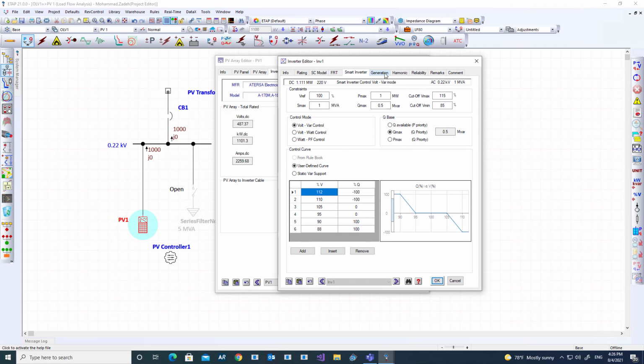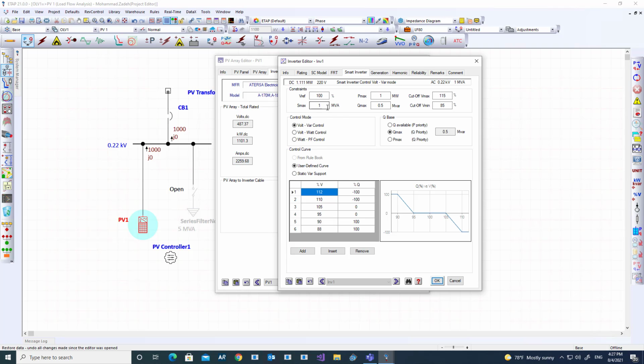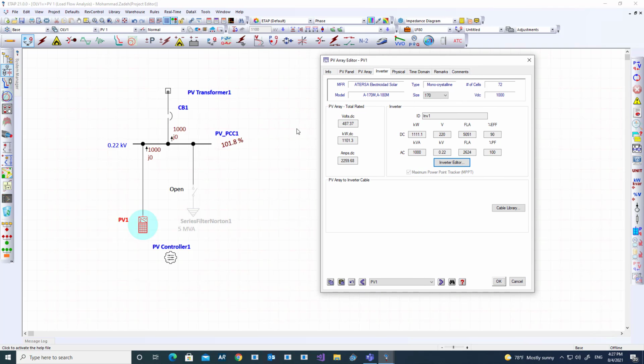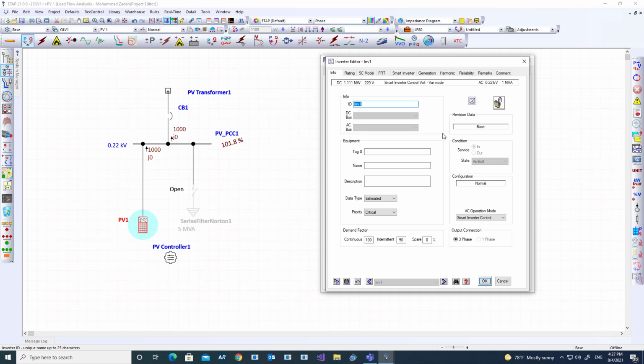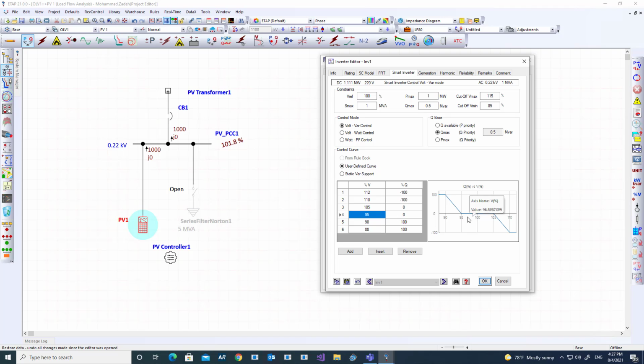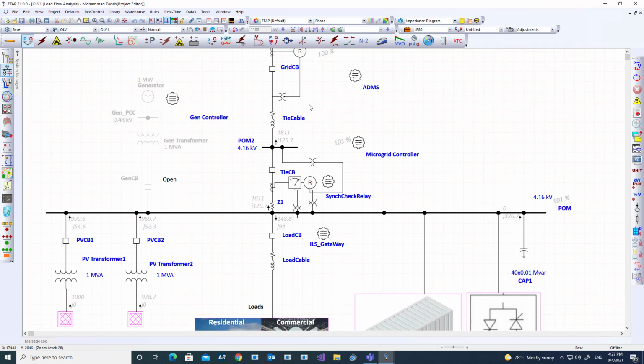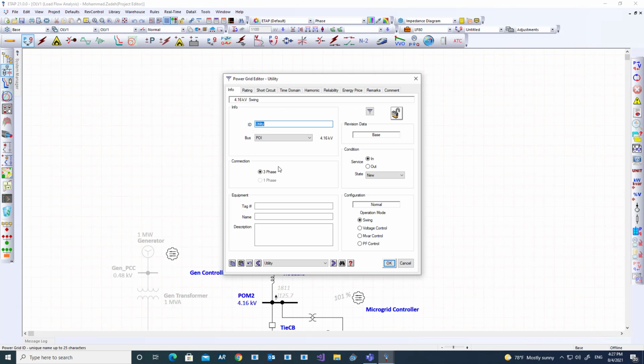So I have an inverter right now that is set to 1 megawatt generation. It has a 1 MVA rating as well, so no room for reactive power at this moment. The voltage of the analysis is also about 101. If you look at a smart inverter at 101, there is no need for any reactive power injection. So things are good.